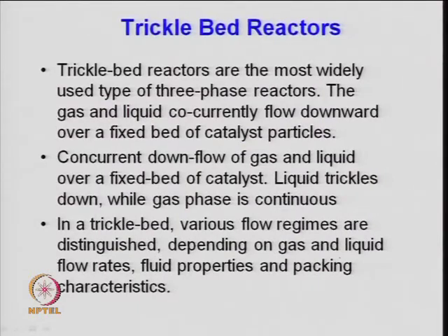I was just talking about the trickle bed reactor. Again, as I said, the hydrodynamics is very important, to decide the gas flow and liquid flow rate or superficial gas velocity, and then the holdup of gas and liquid. But these trickle bed reactors are a type of multi-phase reactor and widely used in the process industry, right.